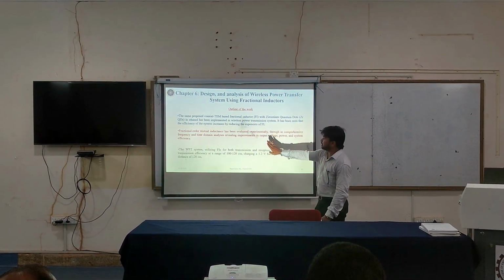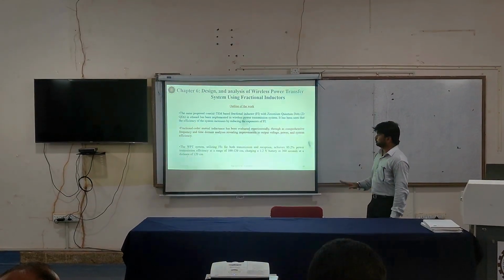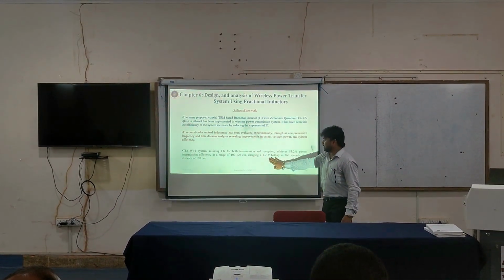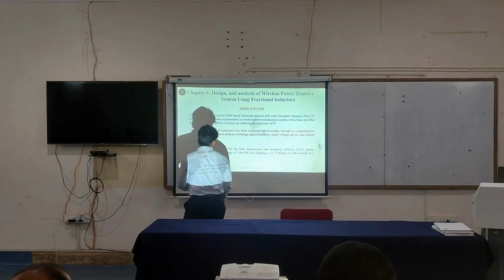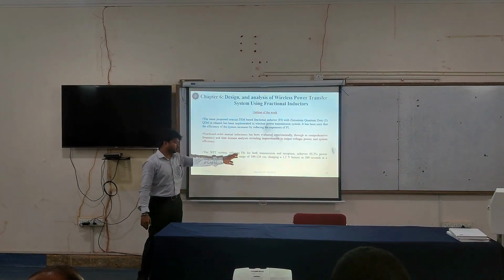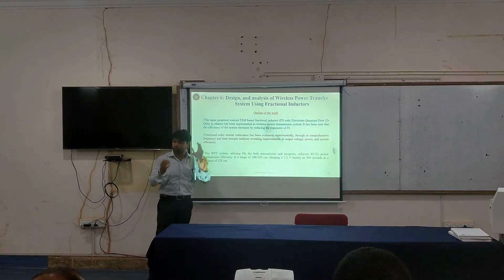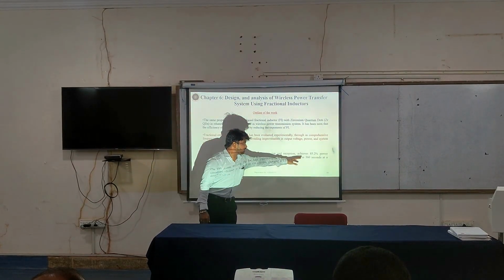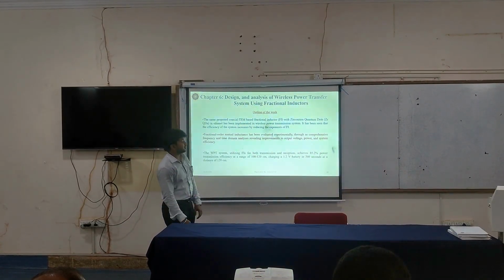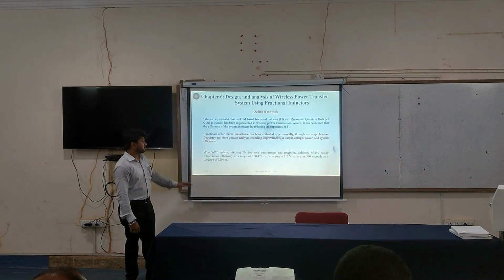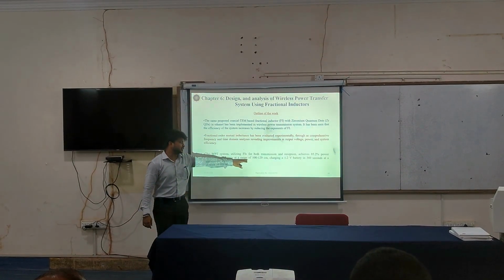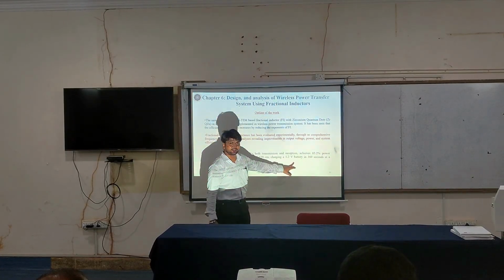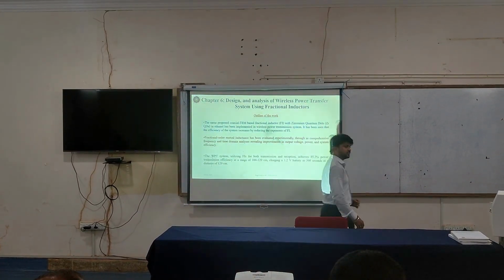The fractional order mutual inductors have been evaluated experimentally through comprehensive frequency and time domain analysis, and it has been seen that the wireless power transfer system utilizes fractional inductors for both the transmission part and the receiving part and achieves a maximum efficiency of 85.2% while transmitting energy at a range of 100 to 120 cm, charging a 1.2 volt battery in just 360 seconds.